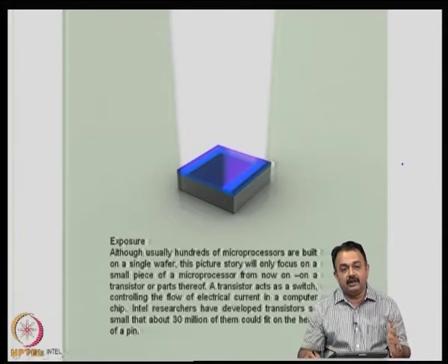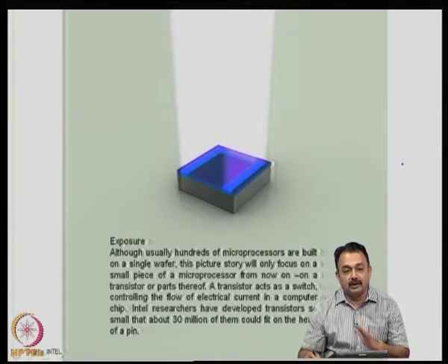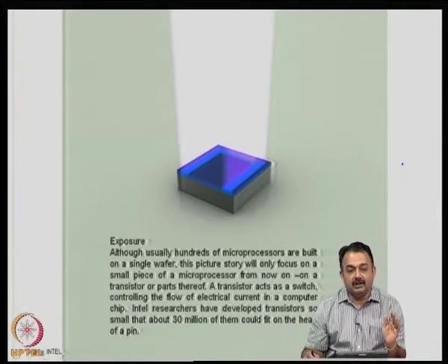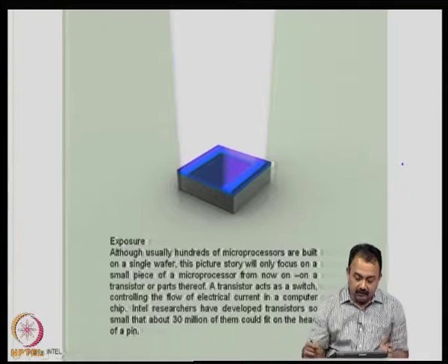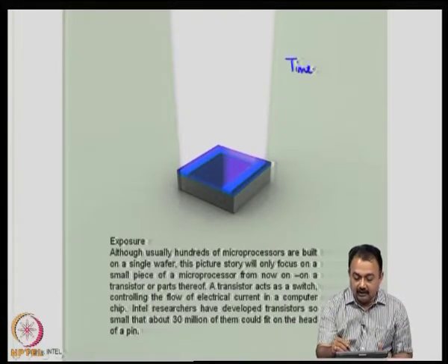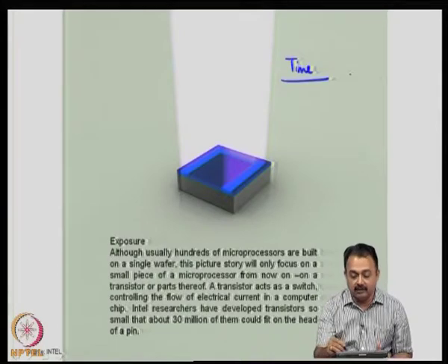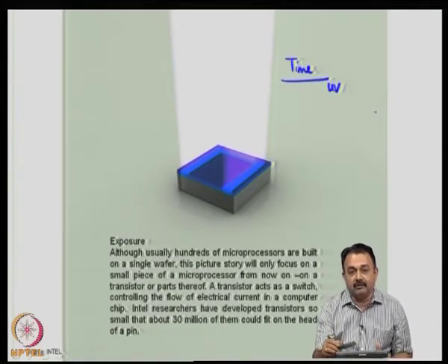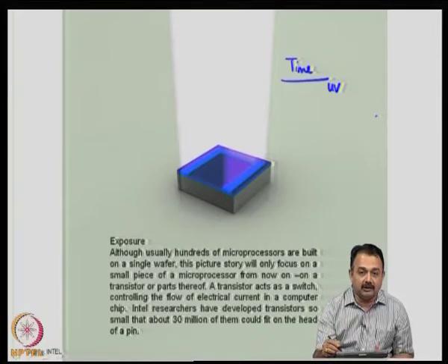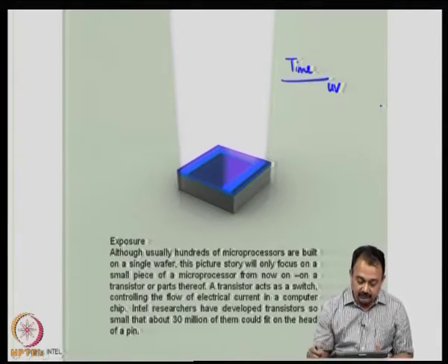So, along this entire exposure process, you do not want any change, any dimensional problem. You do not want to lose any features. And two things, one is the thickness of the photoresist and the time for exposure. Time is also very important. You can't keep exposing the photoresist material to UV light for an indefinite period of time. So, this is also recommended by the manufacturer. All these properties are interrelated, and to get a good image with a high resolution, you need to work on all these issues.